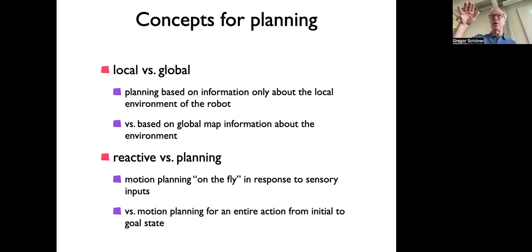For instance, even a docking behavior requires that. Docking behavior could be something like your robot vacuum cleaner docking. To go to the power station, it has to drive to a particular position, but also be oriented so that it contacts the battery. And that will be done by approaching the docking station, you can imagine, at a little bit of the right angle, so it can actually do that correctly. It can't rotate on the spot sometimes because of the mechanics of the docking station. And that requires some real planning, because you have to plan to go a little bit out and then come in. You can observe that if you have a vacuum cleaner of that kind.